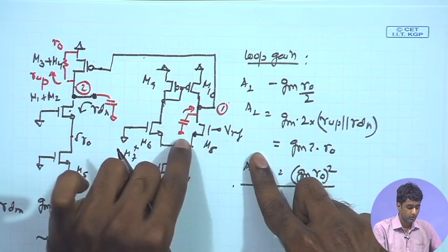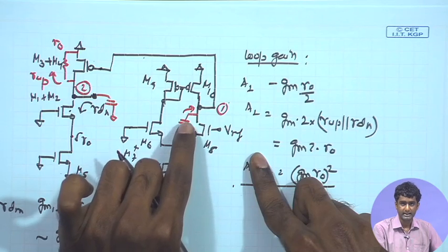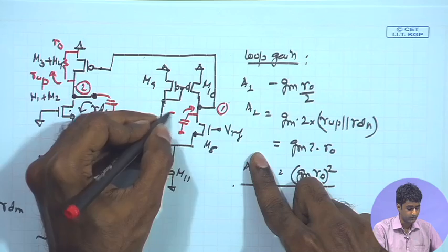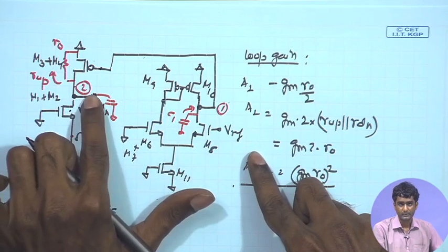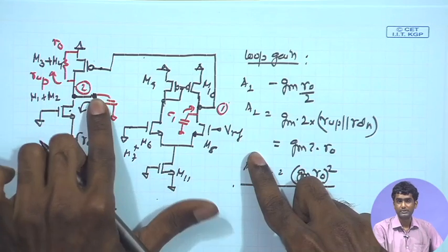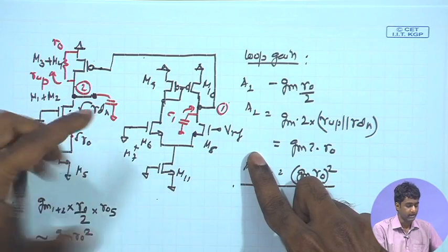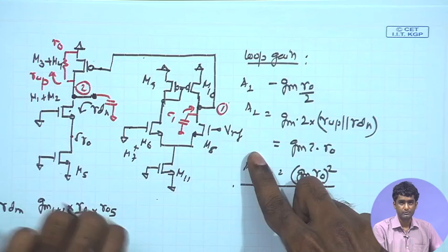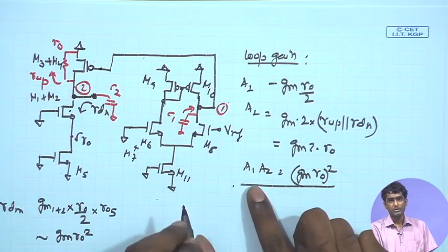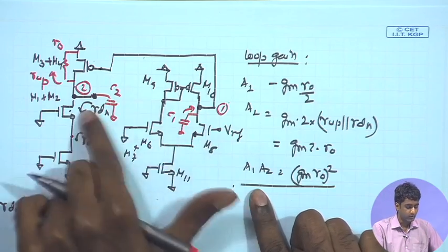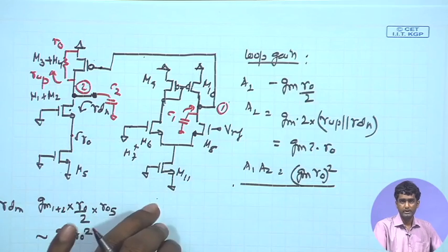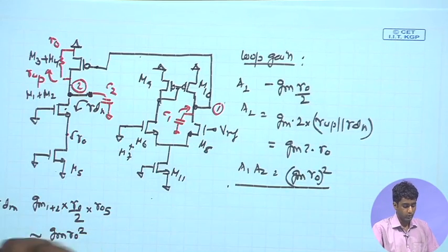So, accounting for all those, we can figure out the overall parasitic capacitance between this particular node 1 and AC ground, and that will give me total C1. Likewise, at the output node, we can find out the total effective parasitic capacitance between the output node and AC ground by counting the contribution of parasitic capacitances for all the transistors, and that is going to count as C2. And we also have the R equivalent at these 2 points. I will call this R1 and R2, and that is how we are going to get the 2 poles P1 and P2 at these 2 points.